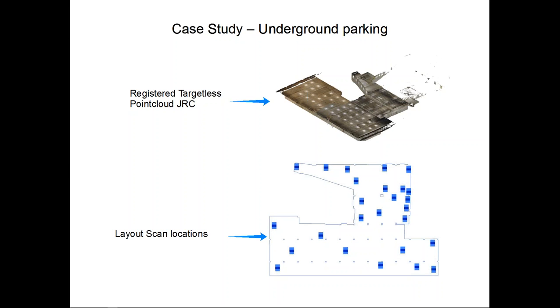Because the scanner itself is a dumb instrument, but very focused on gathering massive amounts of data all around, the total station gives it the knowledge to know where it's positioned in space. So between themselves, the scan positions get that information usually from a total station.